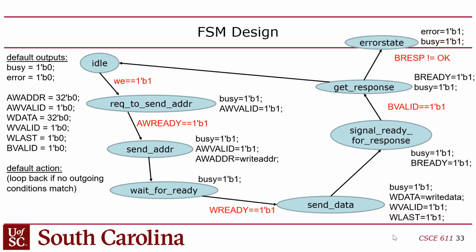So I came up with a preliminary state machine, though, that will make this work. The state machine basically has a state for each one of the steps that you have to take. Now keep in mind that the inputs to this state machine are actually a mixture between the application inputs and the bus inputs. Because, for example, to get things rolling, I have to wait for write enable to be 1. So this is my application logic. This is like your stuff.